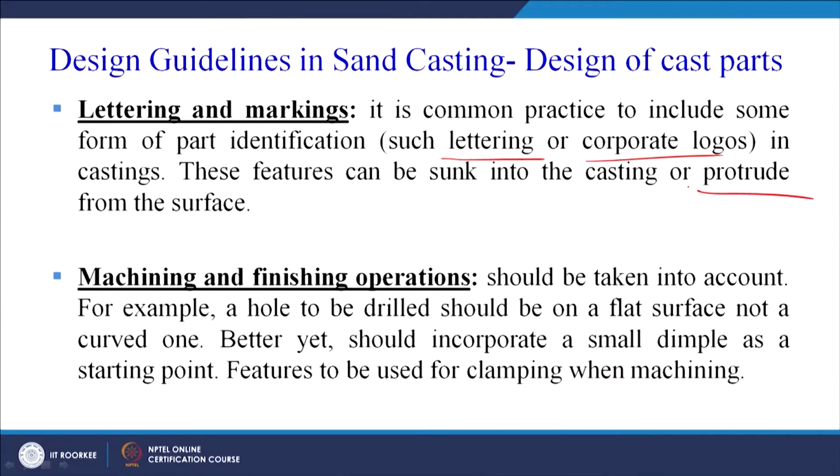So they can be protruding from the surface of the casting. So either they can be made into depression or sunk into the casting, or maybe protruding out of the casting, just to indicate the product belongs to X, Y or Z company. Then, as I have already told, machining and finishing operations should be taken into account.